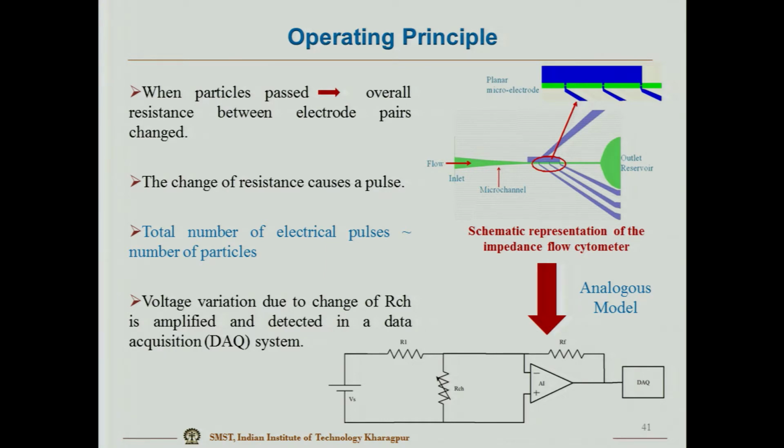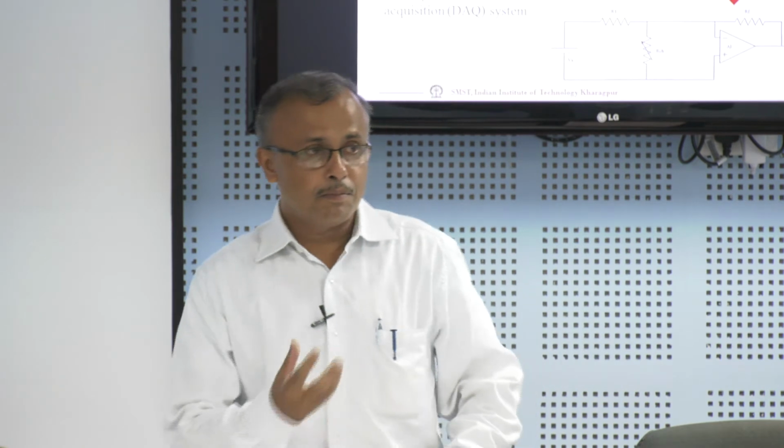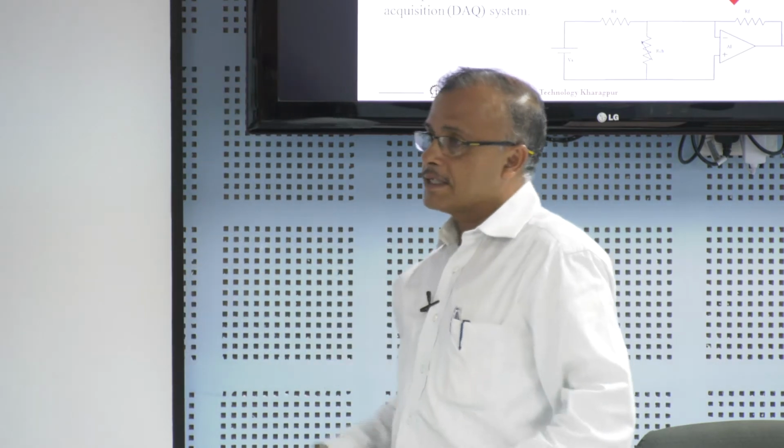Okay. But along with the media, sometimes, because the concentration of the cells is very less, one particle flows, either it is a particle or it can be a cell also. So, what will happen to the voltage? The voltage will change. With continuous flow of fluid there, accordingly you have a voltage. Now, in addition to the fluid you have some cell or some polystyrene bead passing. So, depending on the dielectric property of that particle, that voltage, that signal will change.